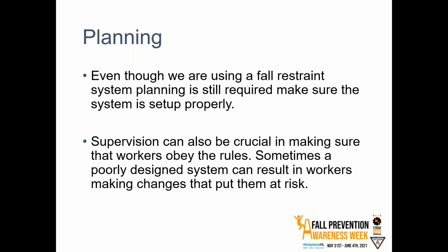The reality here is that the fall restraint system has to be set up just so that the worker doesn't have, again, that extra bit of room that really would just be a tiny bit of extra room that would be required to cause them to fall. So again, there's requirements that need to be considered. And one of the most important ones, arguably, is the length of that lanyard or lifeline, and secondarily, the position of the anchor itself.